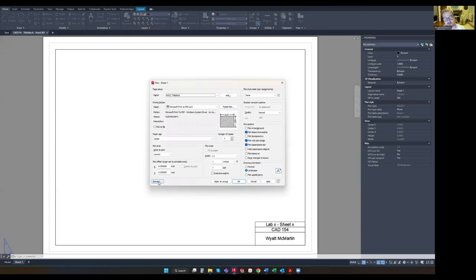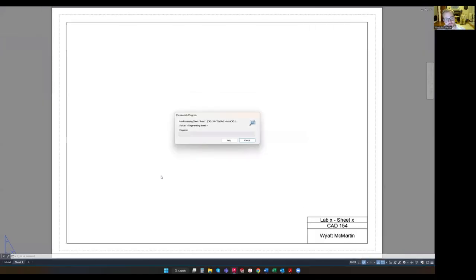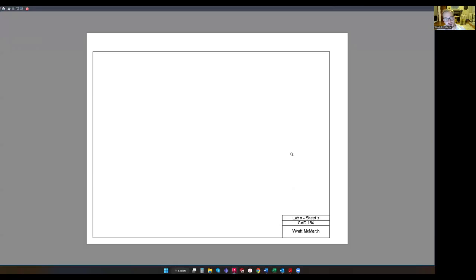Before we plot though, click the preview button and just check. So it looks a little funky. And I knew that this was going to happen. So there's one more little step that we have to do. Remember I said we would have to go back into the page setup manager. Because of the way that dotted border, like the print margins, are set up, we have to offset this by 0.25 and 0.25 so that the plot's perfectly centered on the page. And I will take off points if you plot like this. I want you to plot it centered perfectly in the page.